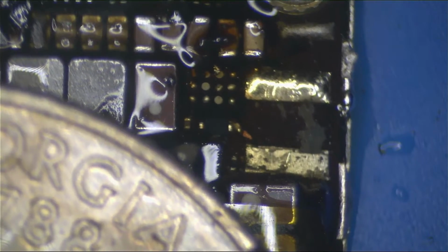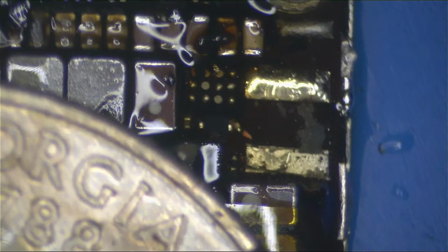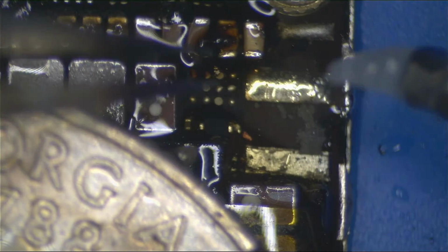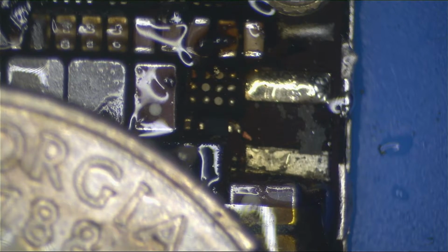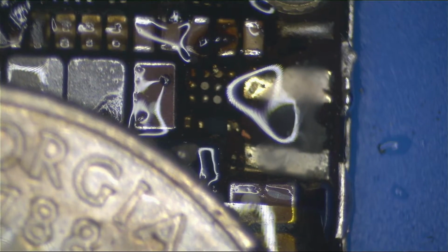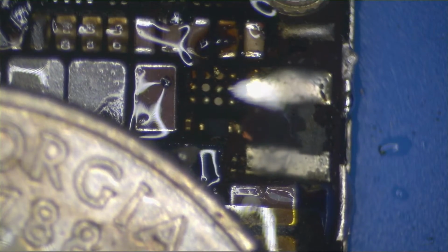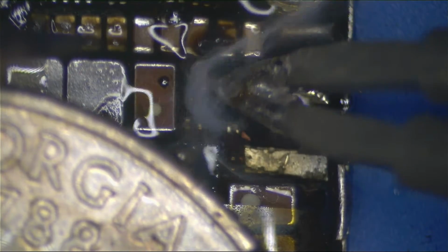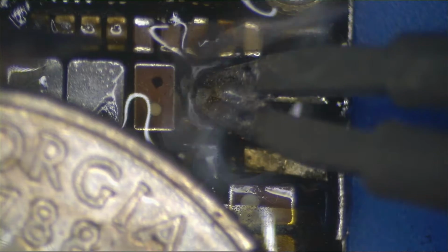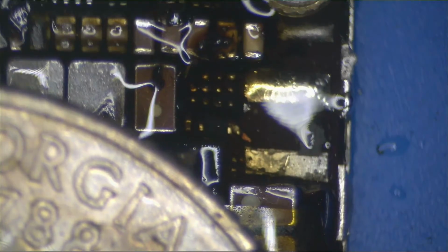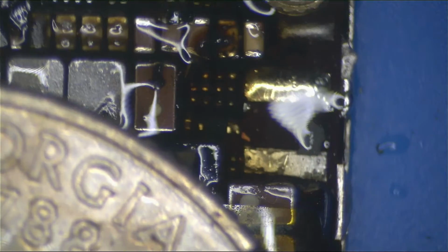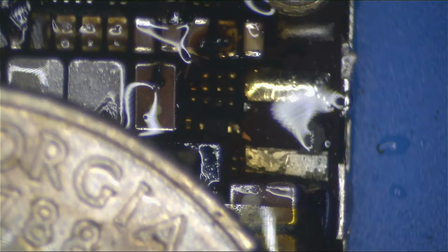Alright, so now we want to start cleaning up the pads a bit so we can put the new IC on and the new coil. First things first, a little bit of flux. And then you're going to take your iron tip, add some leaded solder in there and just start cleaning up the pads. You don't have to get them perfectly flat. I don't bother really wicking them because it's such a small IC. I generally only wick larger ICs. Smaller ones like this, I can usually get away most of the time without wicking them in order to get it flat.